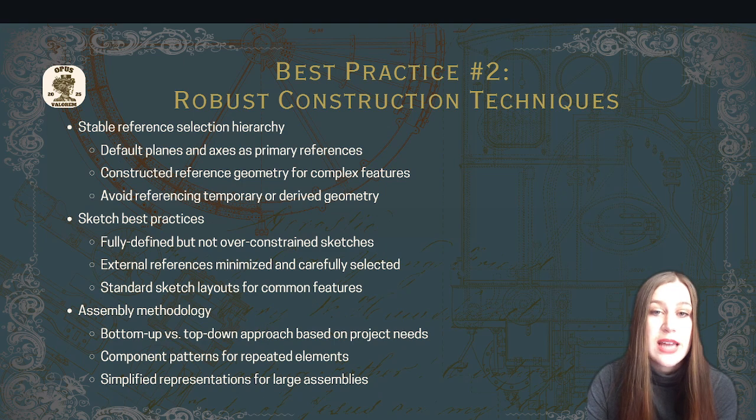Firstly, use a stable reference selection hierarchy. Set default planes and axes as primary references. Construct reference geometry for complex features. Avoid referencing temporary or derived geometry.